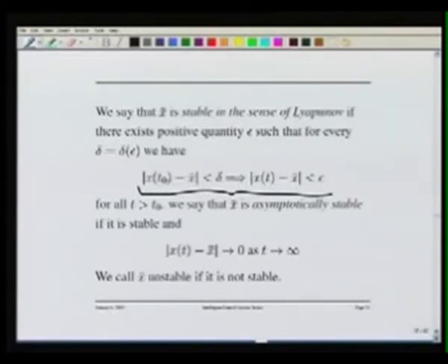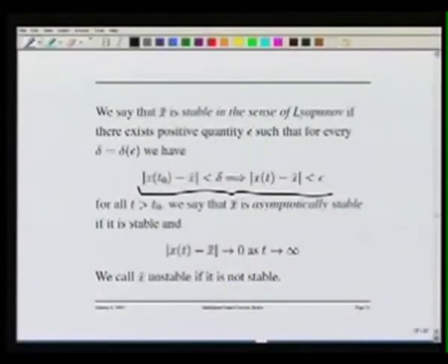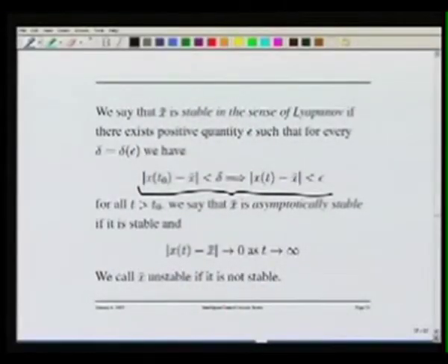After you disturb the system, I relax it, that is, the system dynamically evolves, and after evolving, what happens to the system states? If the disturbance that I have given is less than delta, I cannot infinitely disturb the system and then conclude that the system still remains stable. So, I assume some value delta, an upper bound by which I give a disturbance to the system.